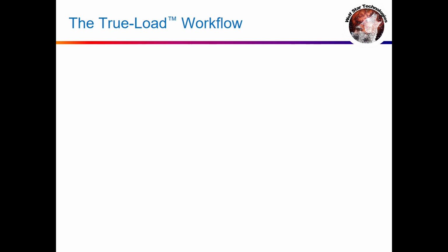So here's a workflow for true load. You're going to start off with an FEA model like normal, but rather than coming in with just a single unit load case that's a complex loading, I'm going to have you take your loading and break it into a series of component loads. So an X component of load, a Y component of load, a Z component of load, maybe a pressure load, maybe a thermal load, maybe an inertial load.